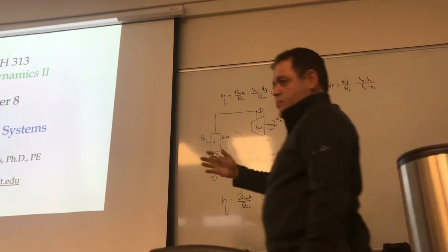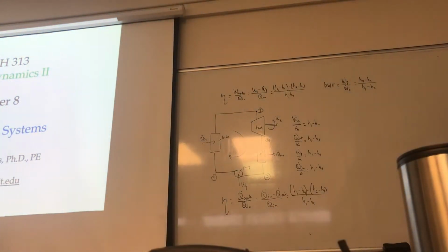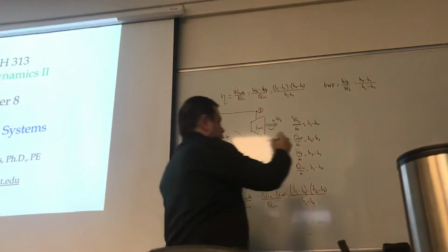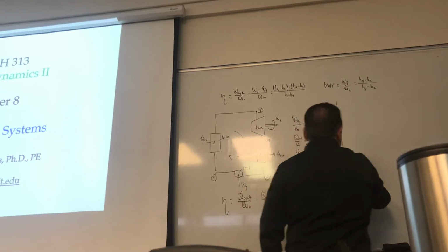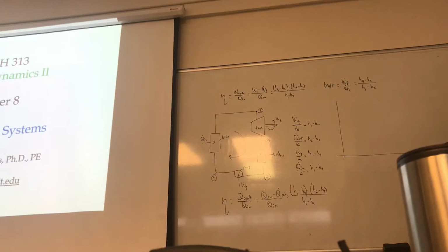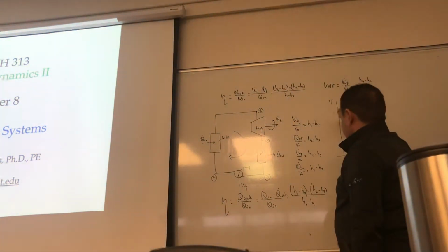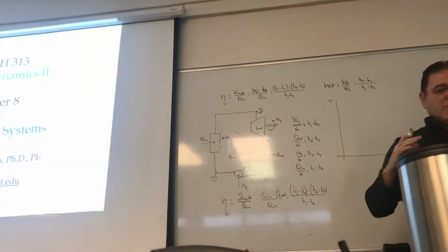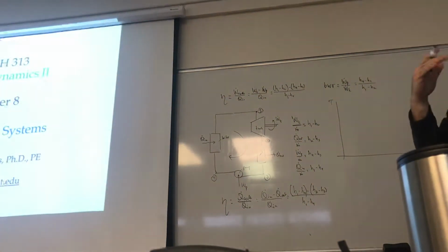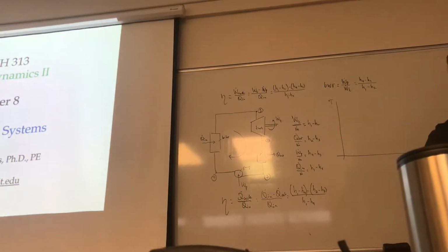See, you can answer so many questions by doing that. Now, in addition to drawing a physical cycle like this, we also typically draw along it a temperature versus S diagram. Why temperature versus S? Because we have two constant pressure processes and two isentropic processes, right?